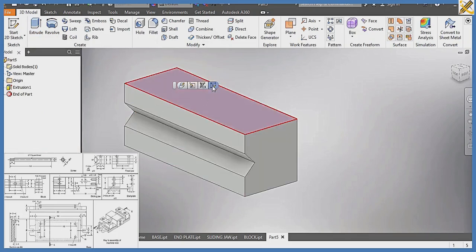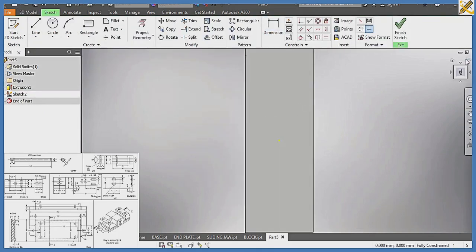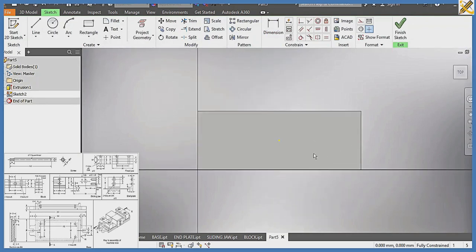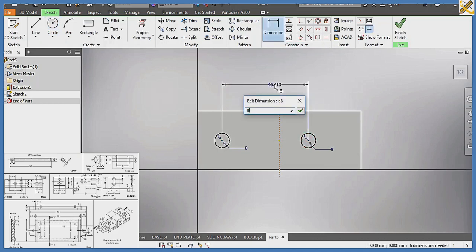So clicking on this view, creating that sketch, I'm going to tilt this way to get it better. All right, so I'm going to pick my line, hidden line for that matter, then locate the midpoint right here, produce this line right there, negate the hidden line, pick my circle, circle of diameter 8. So locating the midpoint there, diameter 8 first of all right here, then diameter 8 right here also. Picking my dimension, the distance between these 2 circles, circle 1 and circle 2, is 50, enter.